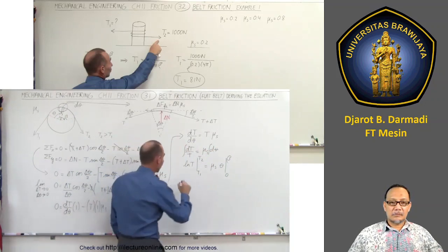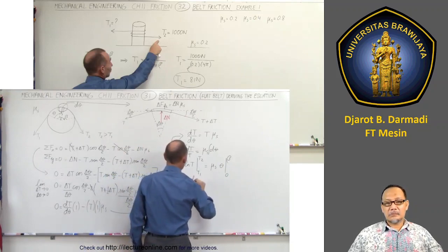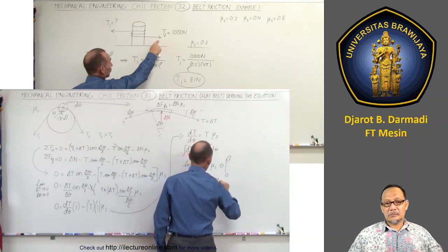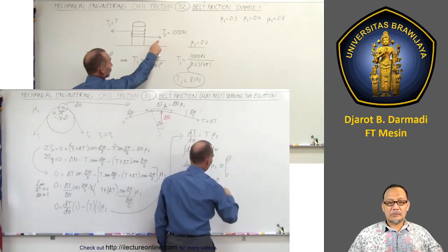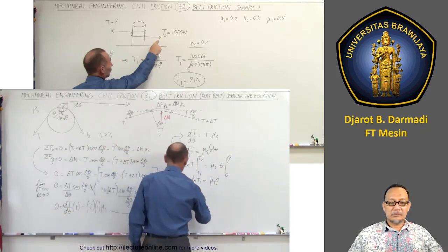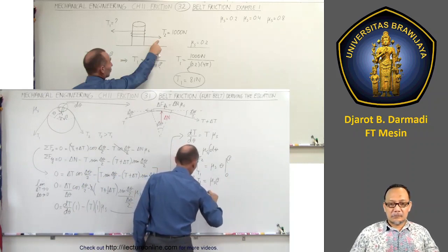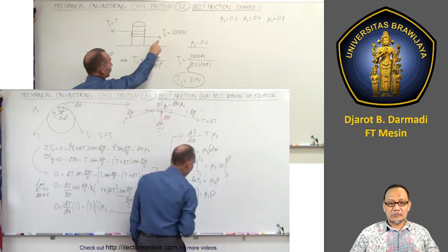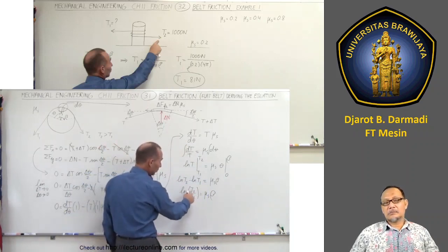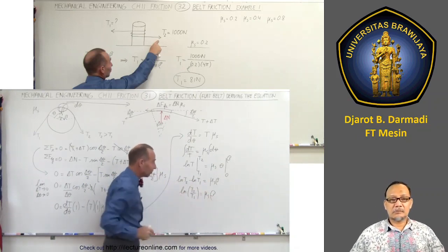So on the left side, we end up with the natural log of T2 minus the natural log of T1 is equal to mu sub s times beta, because when you plug in the lower limit, you get 0, the upper limit, you get beta. And then this can be written as a fraction, so we can say the natural log of T2 over T1 is equal to mu sub s times beta. Now that's a good equation. This tells us the relationship between the difference in the tension between T2 and T1 and the static coefficient of friction and the angle that subtends.